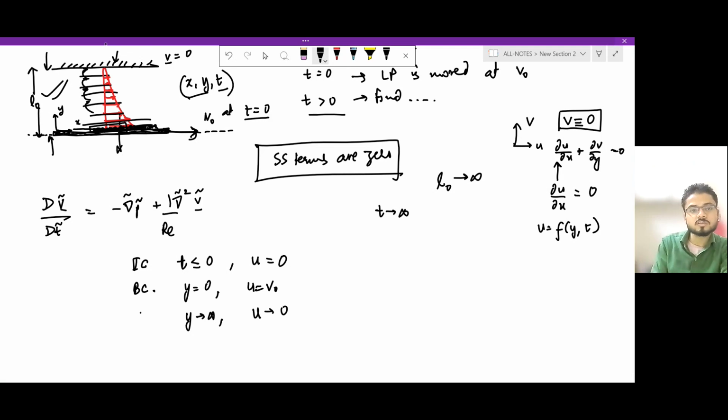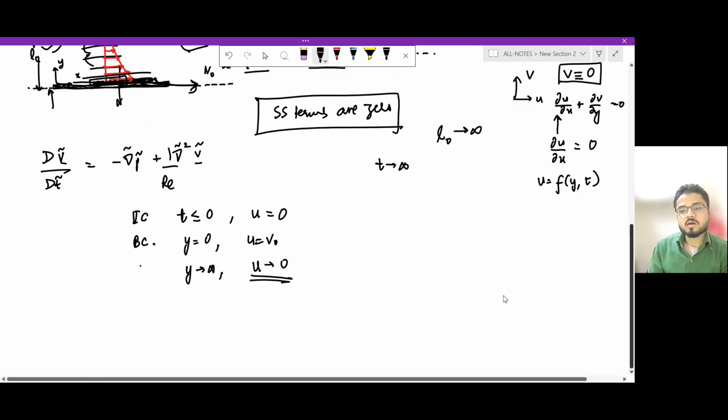Because the closer it is to the surface, due to the sticking property, due to the viscosity effects, the no-slip boundary condition is valid right here for a general surface, and that would imply that the velocity should be 0 at the surfaces.